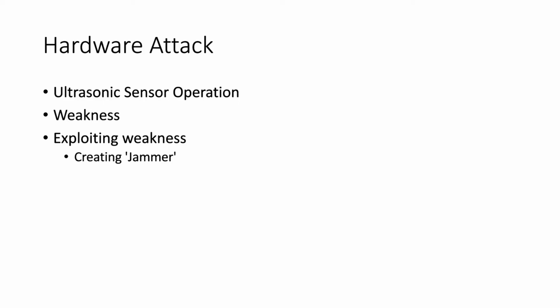and wait to receive the echoes of those pulses back. So the sound waves will go out, bounce off of something, come back, and the sensor will time how long they took to come back. Then knowing the speed of sound and how long it took for the pulses to come back, it can work out how far away some device is. But these have a weakness in that all of them use the same sequence of pulses to send out.